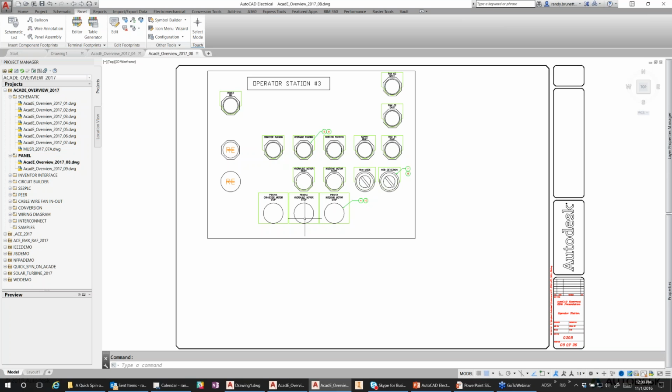And in reality, if we had 1-line drawings, 3-line drawings, hydraulic, pneumatic, and P&ID drawings that electrical can also create with its included symbol libraries, and if a symbol appeared on all of them, all of the different locations would be updated at the same time during that same operation. So literally it can be appearing 5 or 6 times in your drawing and all be updated.